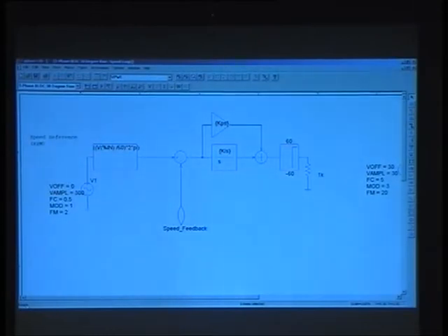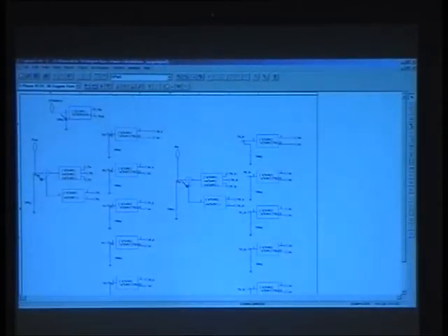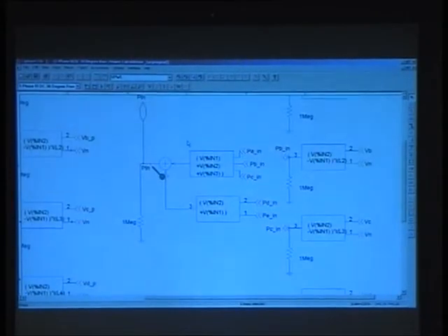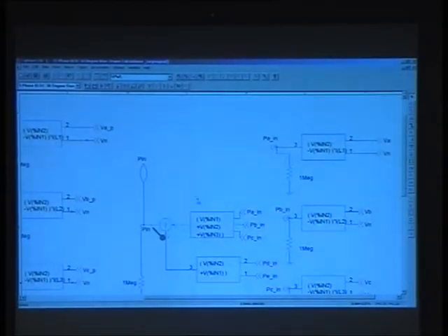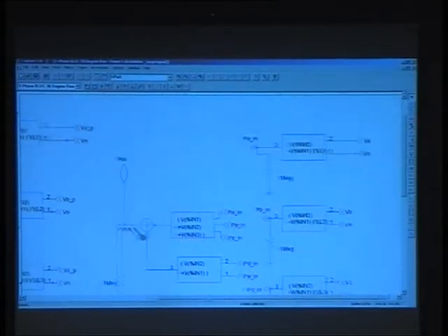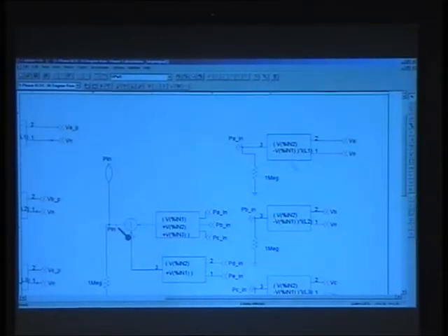Okay, so the torque: we calculate what is called power output, right? The power output is calculated like this. We take the back EMF voltage and multiply it with the current. That gives me PA in, the per-phase power.